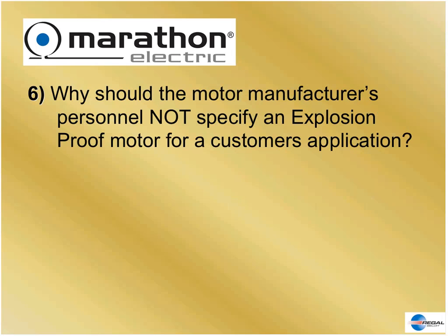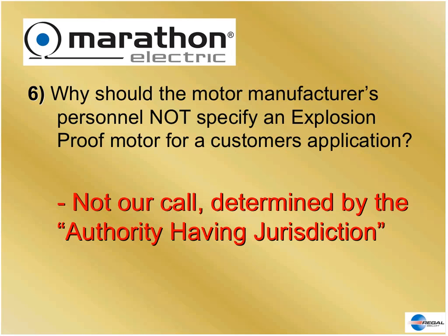Why should the motor personnel not specify an explosion-proof motor for a customer's application? Doesn't mean we can't supply them, but we, as motor manufacturers, should not specify. And you, as customers, should not specify until you get the right information. Why? Because it's not your call. The authority having jurisdiction over that installation and startup is the person that makes this call. Now, it could be a safety engineer, it could be an insurance engineer, it could be a consulting engineer, it could be the Corps of Engineers, it could be the fire marshal, it could be a city engineer, it could be anybody, but whoever's got that authority makes that call, not you.